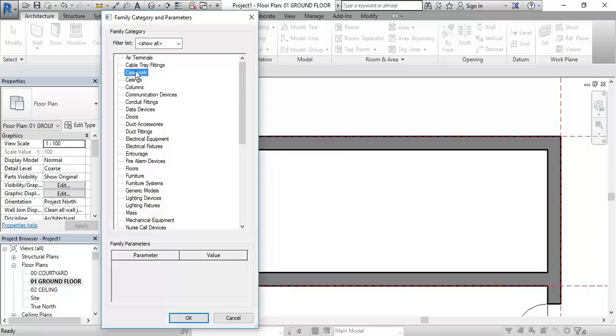There's another one for built-in furniture. It's called casework. And it's just the American term for built-in furniture, essentially. So use casework if it's built in, and most of the furniture you design will be built in. Things that aren't built in, you'll get from a furniture maker. But the things that are built in, you'll design from scratch. So I'm going to use casework, and that's a good all-round category to use for most of your built-in furniture.